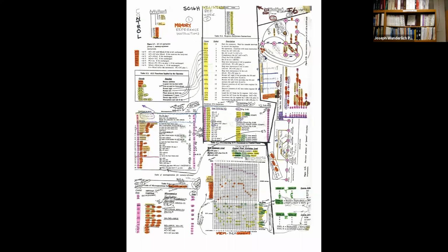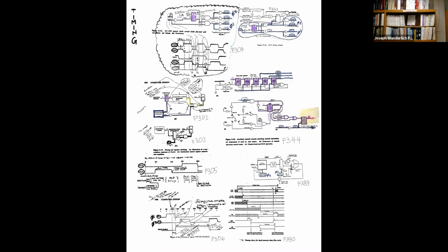The next slide here is the timing. So you have a main clock circuit, and then you parse that into other clocks. You see the timing diagrams. You hear me always stressing how important it is to have timing diagrams with FPGAs and other devices when we're